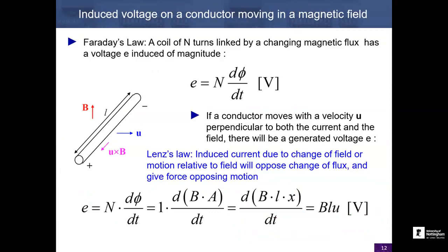And then the other side of the coin, based on Faraday's law, is our expression for induced EMF. Our induced EMF is equal to B times L times U. So EMF is equal to the flux density times the length of the conductor times the velocity of movement through that. That's just an expression of Faraday's law, but it's the other side of our coin. Just like we've talked about how we can get a mechanical force from an electrical system, this tells us how we can get electrical potential and ultimately electrical work out of a mechanical motion of a conductor through a gap.